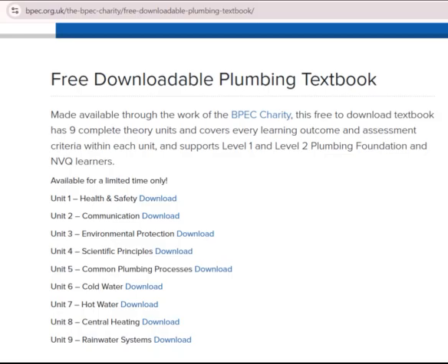Below is a table of some of the common materials used in the plumbing industry. The relative densities of common materials. Product relative density. ABS, extrusion grade 1.05. Brass, cast rolled 8.4, 8.7.